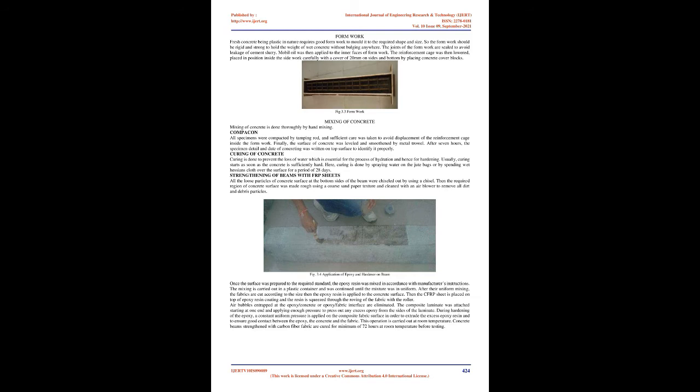Advantages. FRP materials have higher ultimate strength and lower density as compared to steel. When these properties are taken together they lead to fiber composites having a strength/weight ratio higher than steel plate in some cases. The lower weight of FRP makes installation and handling significantly easier than steel. Here, no bolts are required. In fact, the use of bolts would seriously weaken the material unless additional cover plates are bonded on.